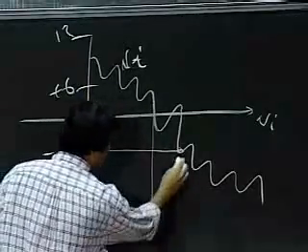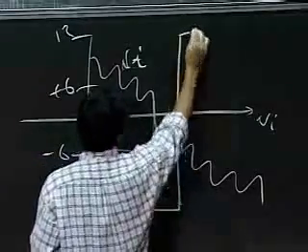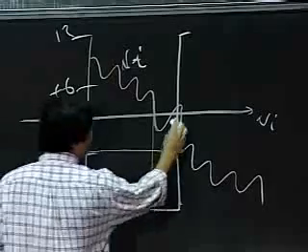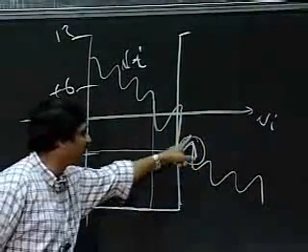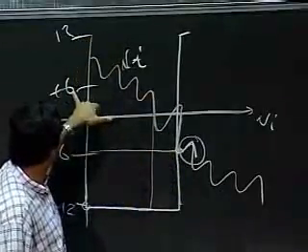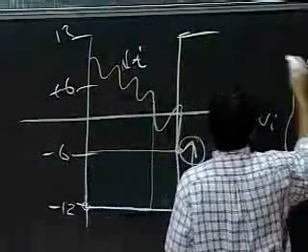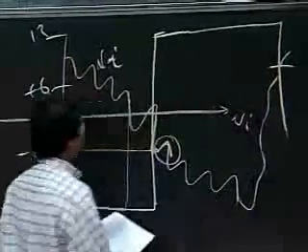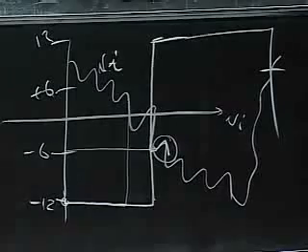So out here, I get to minus 6, and I switch state, and I go up to plus 12. And then this one comes up above -6 very slightly out there, goes above -6, nothing happens because the next change will happen only when the input goes to plus 6. So eventually the input gets to +6, then I'm going to change state again. Okay? So this is actually a really cool property and something that is completely non-obvious.